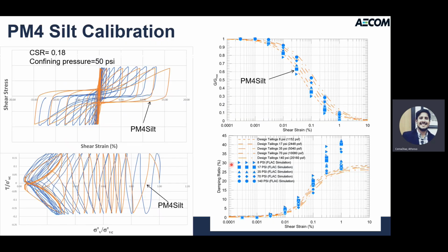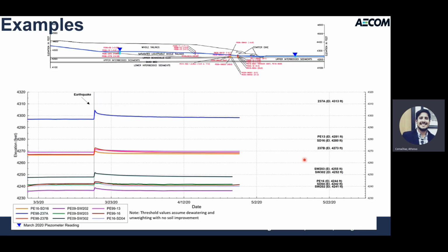And in order to evaluate liquefaction under cyclic conditions, we have to really look at the coupled model, in which we model the stress-strain cyclic behavior. We model the stress path due to the pore pressure generation from the cyclic loading, and we also model the modulus reduction and damping curves, which are important to understand the level of amplification that we have. And those are confining pressure dependent. And once we have our model, we have to compare with our measurements.